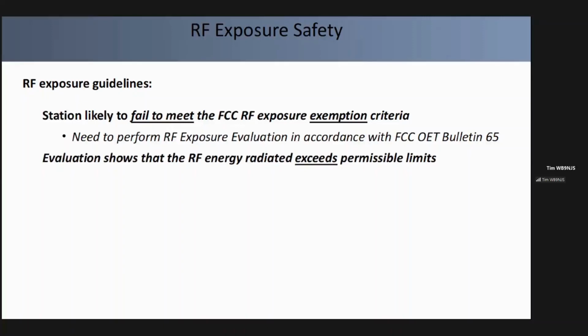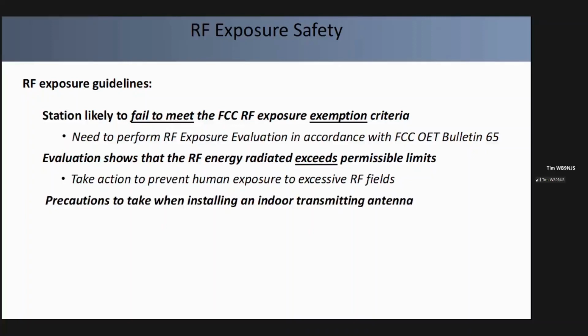So what happens if that evaluation shows that RF energy radiated exceeds the permissible limits? You went through step 1, okay, I did the evaluation, it shows that the energy exceeds the permissible limits, now what? Well, at that point, you must take action to prevent human exposure to excessive RF fields. So when the evaluation shows RF energy exceeds the permissible limits, you have to take action to prevent human exposure. This is kind of parallel to that.